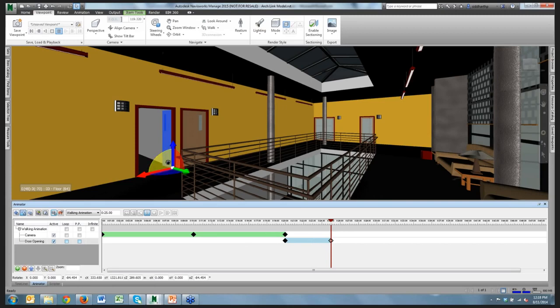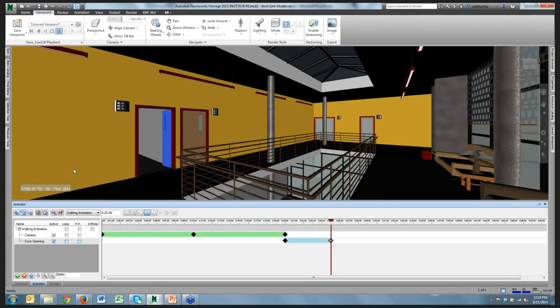So when I was manipulating the axis and positioning it, I was just orbiting around it like I normally would. And once I have it set up correctly, you can then just do that manipulation and capture the keyframe, and it will bring you back to the original viewpoint that you had used for your animation. So with this done, what I'll do is I'll turn off my rotate animation set again. I can deselect my door, and let's play that animation from the start to the end again.